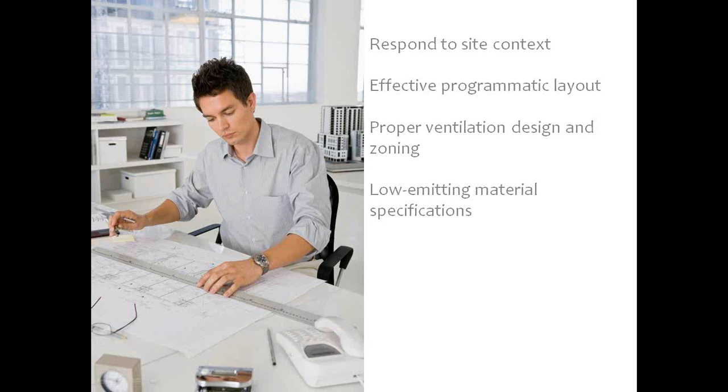When you're building a school, typically the cafeteria area should be isolated from the rest of the school because of all the cooking and cleaning processes that are constantly going on. You definitely wouldn't want the air to be recirculated through the classrooms that's coming out of the science laboratories where they're dealing with chemicals, from the art laboratories where they're baking things in the art kilns and things like that.